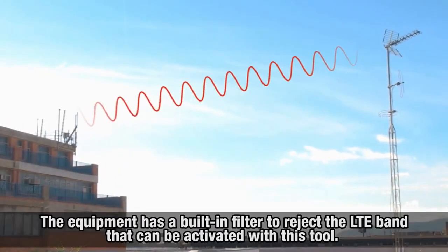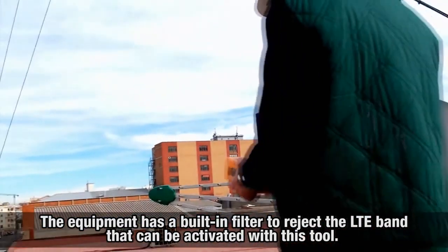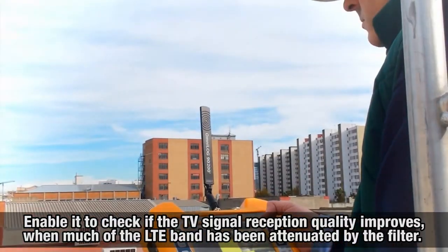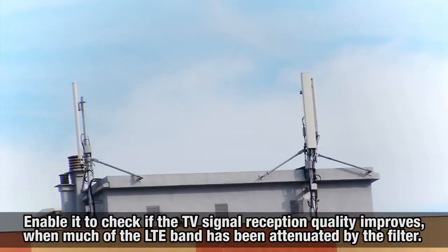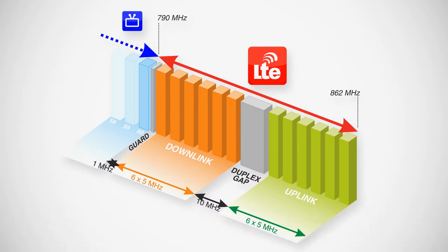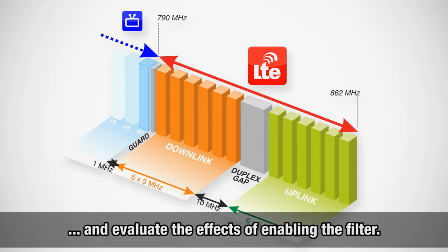The equipment has a built-in filter to reject the LTE band that can be activated with this tool. This filter can be enabled to check if the quality of the TV signal reception improves when much of the LTE band has been attenuated by the filter. With this tool, you can measure the MER of a digital terrestrial channel, presumably affected by an LTE signal, and evaluate effects of enabling the LTE filter.